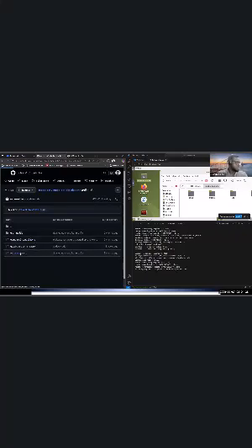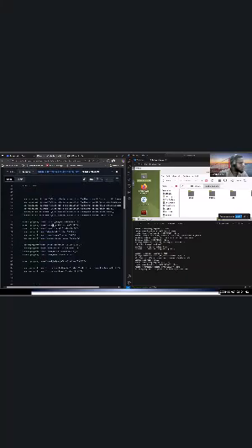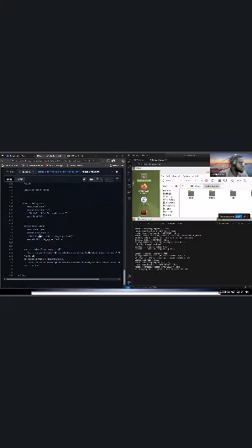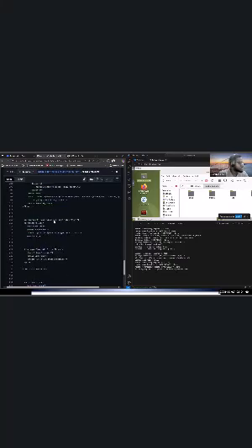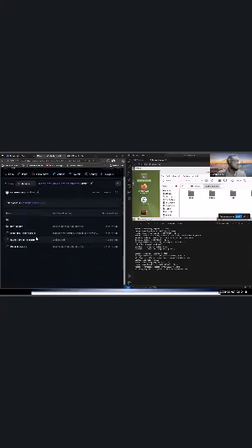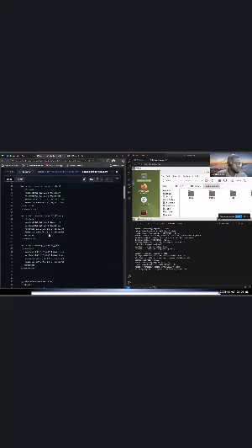Let me go to the robot description. You see the links, the material name, and below, the xacro, which is just including the different sensors: camera, sonar, and so on. Then the joints and the links. This is where all the links and joints of the robot are described. And for Gazebo, the xacro: in robotics and in ROS, most of the files you use and build on in ROS projects are xacro files. That's why you see robot XML and xacro. It's basically describing the environment.